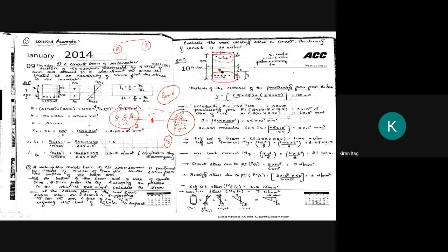So here we have to determine the effective force. Here three persons are pulling the rope, and here 15 persons are pulling the rope. So we want to determine where my center is, whether this ribbon or tag is going this side or that side, or where it is going to stop. Because of that only we are determining the CG for the pre-stressing force.